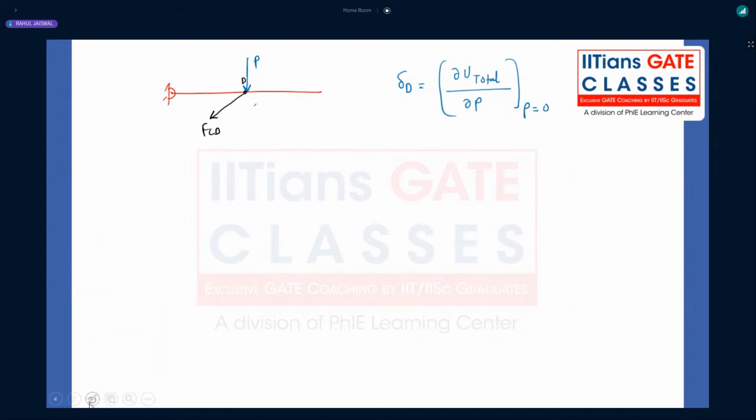So now, when you think of this solution, the load is a uniformly distributed load of W. Here I'm just writing the length as L. I know that it is 1 meter, but I'm keeping it as W and L, in the form of W into L. So what is the moment about A?